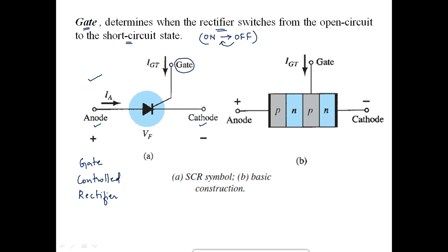In the case of JFETs and MOSFETs, the gate current Ig was 0, right? Because of which it actually acted as a voltage controlled device. But here the gate current literally flows. So it's not a voltage controlled device. Please bear it in your mind.